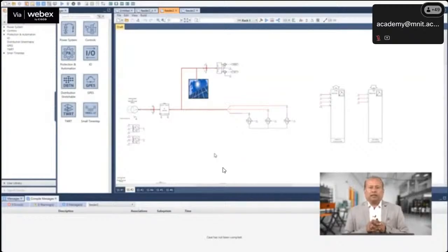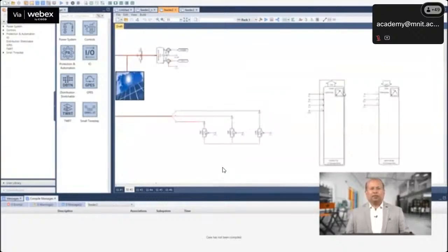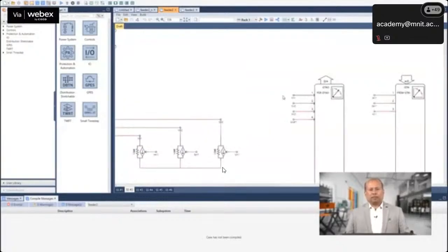This instant has been recorded during the PHIL validation of the BESS connected with the IIT Roorkee distribution network. We have physically connected a BESS converter with the IIT Roorkee network, and to implement this we have connected the BESS converter to RTDS with the help of the power amplifier using GTAO and GTAI cards.